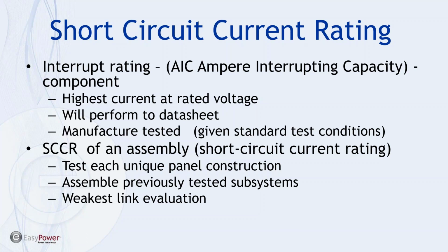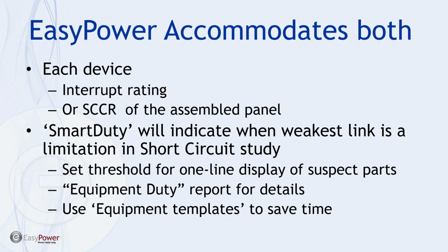In terms of arc flash modeling, EasyPower accommodates both in terms of the way the data can be entered in the one line. For each device, we can designate the interrupt rating, or if it's a panel, we can designate the short circuit capacity rating. And in terms of evaluating that, Smart Duty, which is a feature built into EasyPower, will indicate when the weakest link is the limitation in the short circuit study.